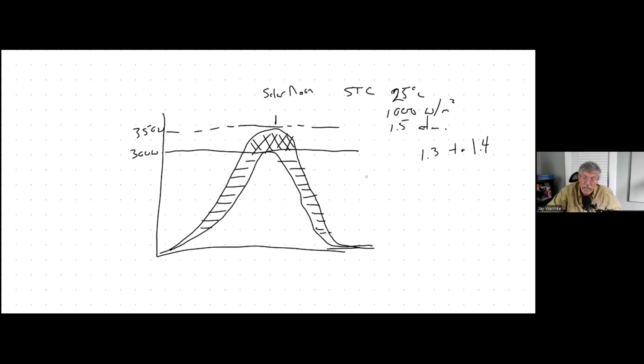Now, as we just saw in this demonstration, the difference between a 10 kW Fronius and a 7.7 kW Fronius is so small that I would probably, let's say this was my 10 kW, and this would be a 7.7 kW if I had my inverter and I'd be clipping. Or I could go ahead and get a 10 kW. Well, with 10 kW, you get the benefit of those shoulders, but you also then don't clip off anything anyway. So that's kind of the best of both worlds, given the economics that we found on this website. I'd go with the bigger inverter. You never get into a problem.